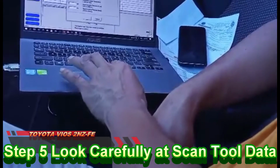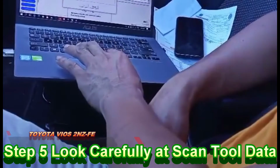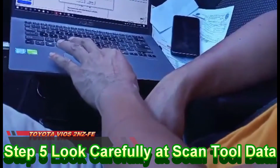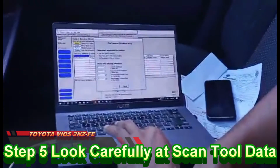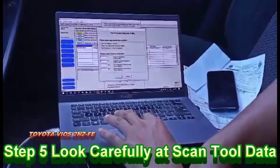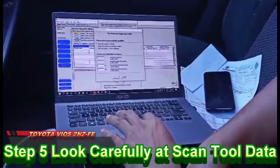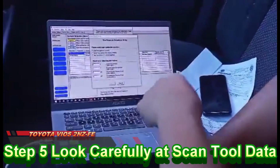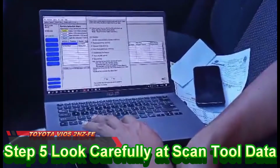That statement does not appear on scan tool displays. The best way to look at scan data is in a definite sequence and with specific, selected bits of data that can tell the most about the operation of the engine, such as the following. Engine coolant temperature (ECT) is the same as intake air temperature (IAT) after the vehicle sits for several hours. Idle air control (IAC) valve is being commanded to an acceptable range. Oxygen sensor (O2S) is operating properly.